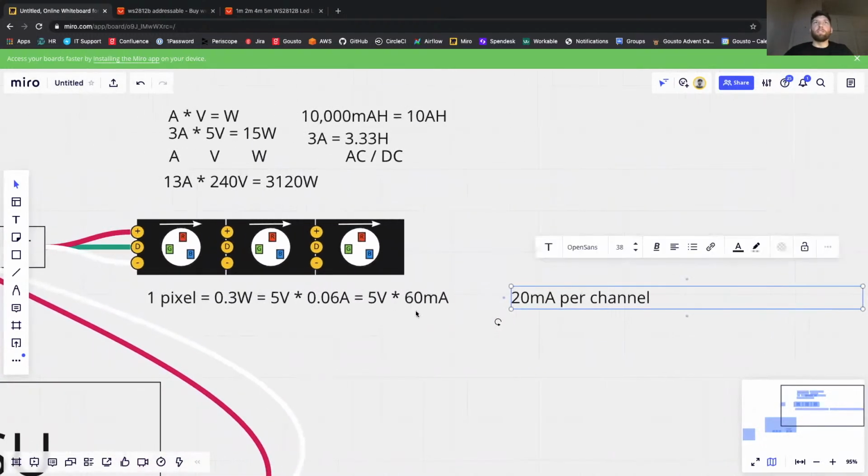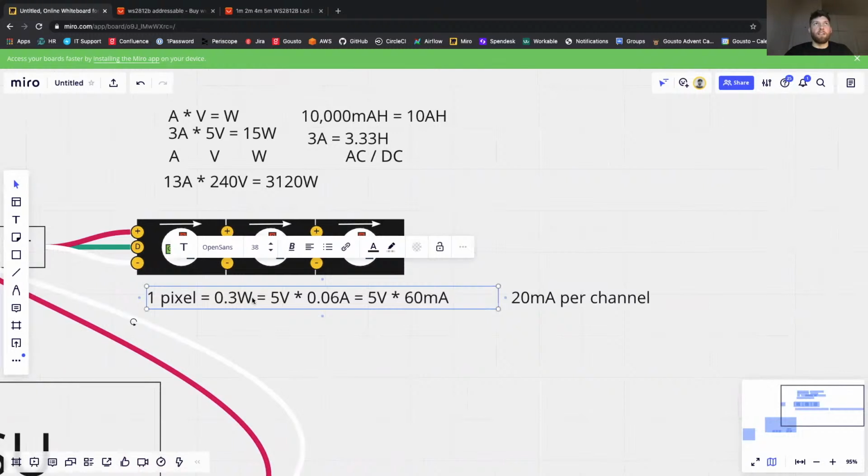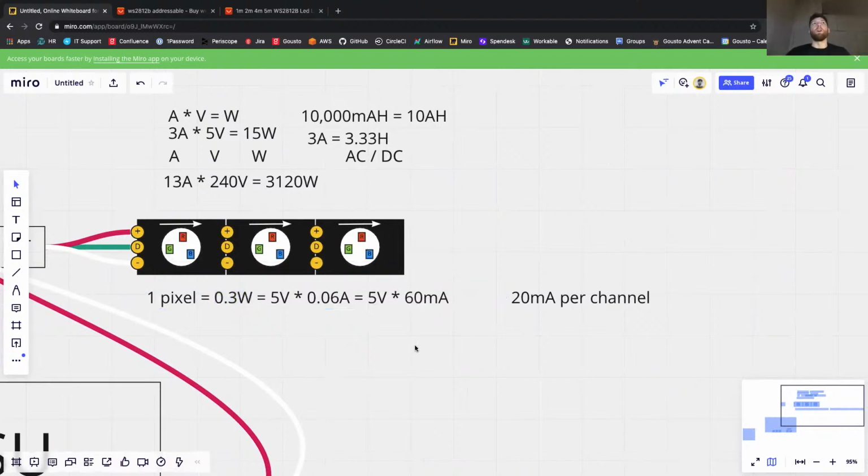And the reason this is listed as the wattage of the strip is that this is the maximum current that can be drawn, the maximum brightness that can be set for each channel, and essentially full brightness white is what we're going to get out of it. So whenever you see wattage or power ratings on LED assets or appliances, you can know that it's rating for when the entirety of all of the emitters are set to full brightness white. Okay.